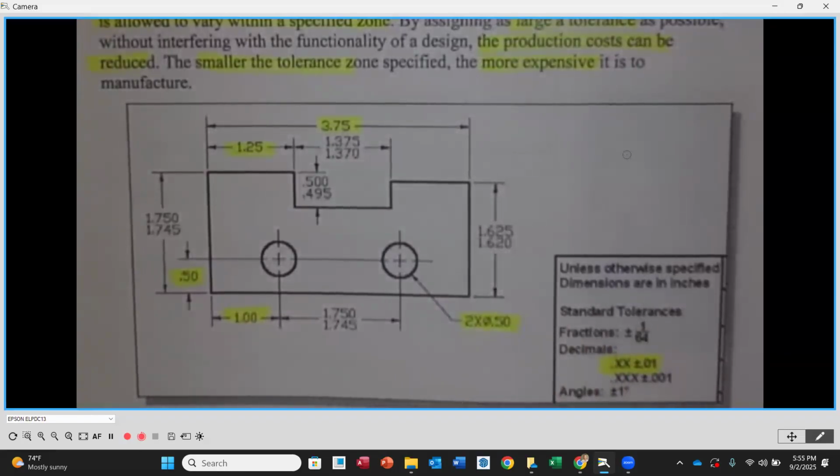Now, that is why it's important on a company level, at WCTC, we have our own title block tolerances. Know what your title block tolerances are. As a designer, you can never change those. That is not an option, because once people know a company's standard tolerances, nobody looks at the title block anymore. And if you all of a sudden do a switcheroo and change the title block because you didn't want to put a tolerance on all the 2-place decimals, no one's going to like that.